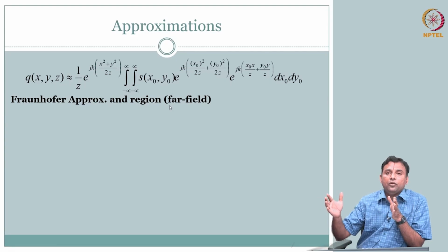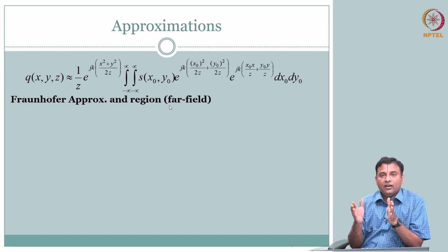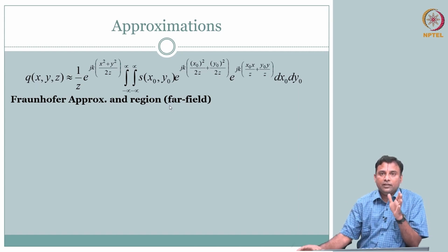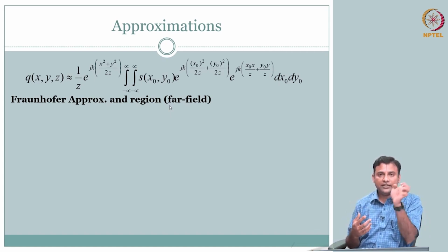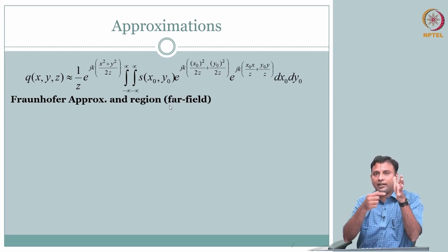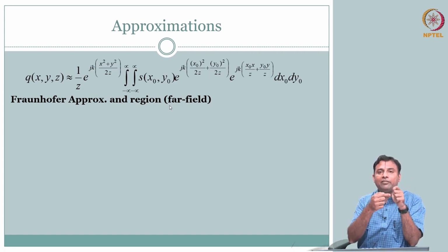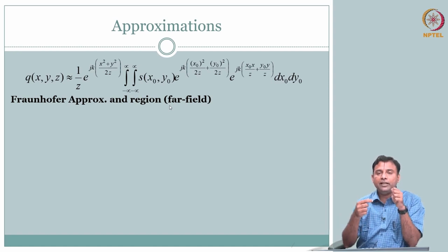How far are you? We should have some condition under which we should say you are far. All this is in relation to where your transducer phase is. When you say transducer phase, you can intuitively guess the influence of this phase is going to be the distance. If I have a bigger phase, I will probably have its influence in a farther region. If this is a smaller phase, probably I will have the influence over a smaller region. So this near or far, you can intuitively guess, is going to be in relation to the size we are talking about.